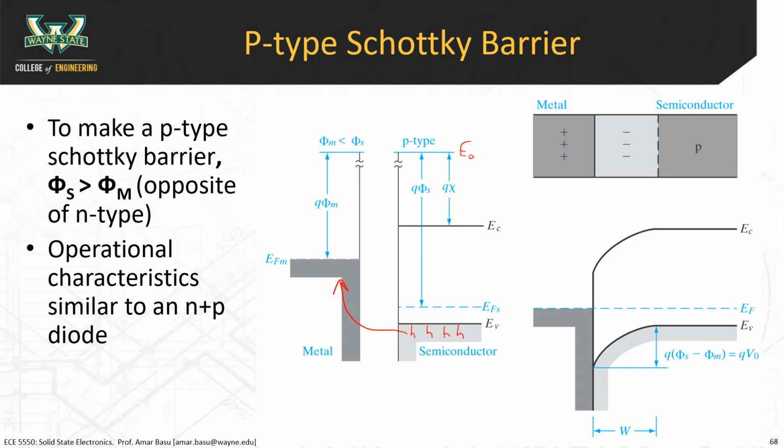Okay. Since the holes have moved over, there's a depletion of holes on the right side of the junction, similar to the electrons. So you imagine what happened. You put the metal and the semiconductor together. The holes in the semiconductor moved over to the surface of the metal, and that's what's causing these positive charges. The holes moved over like that. But because the holes left, you're left with the depletion region. And the depletion region just consists of those negative immobile ions.